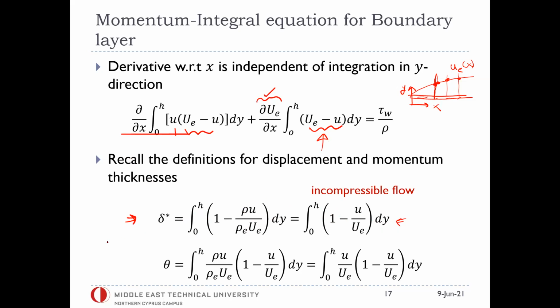Similarly, for the momentum thickness that we defined before, I have u times (U_H minus u), which I see here. So this must be related to momentum thickness. These integrals are actually related to the displacement and momentum thickness terms, which are indeed parameters that I'm interested in.